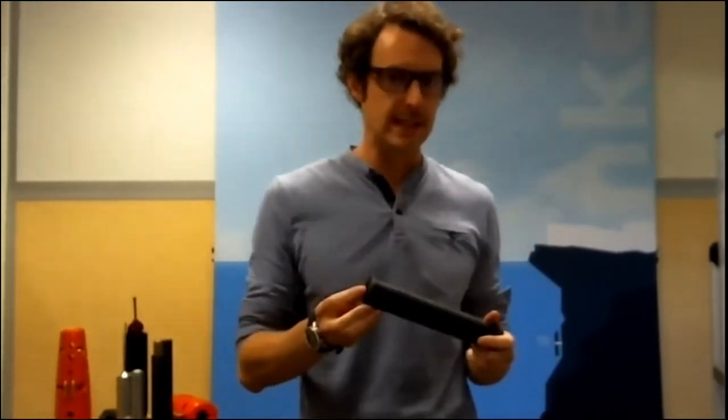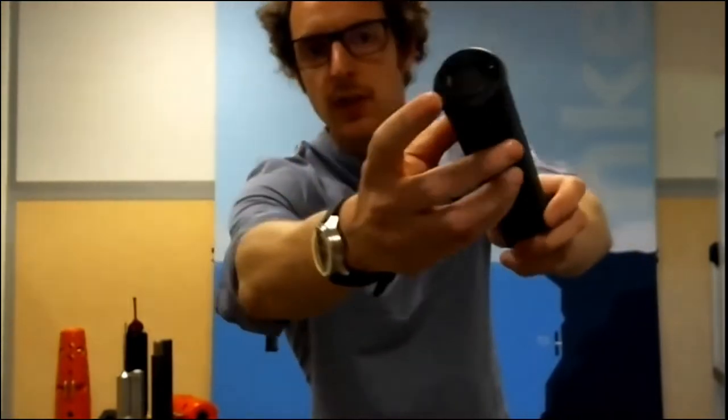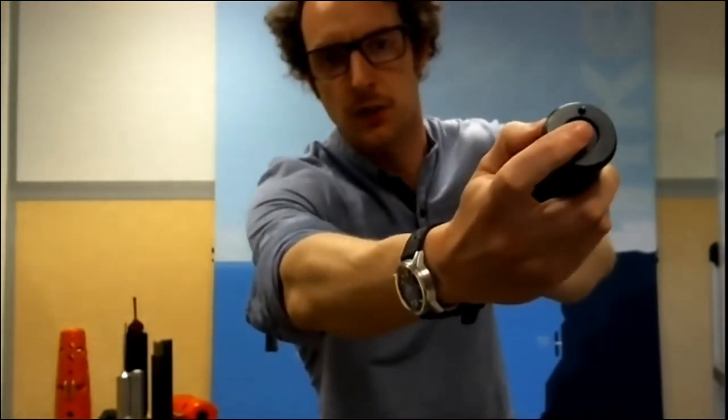So first, now what I'm holding is a Ysense TD, that could also be a Ysense wave. I will talk about this a little bit later. So TD stands for temperature and depth. So all our Ysense have at least temperature and depth, and then more sensors. So this one is just temperature and depth sensor. So you can see pressure sensor here that is behind a protection and specific coating to avoid any fouling to come in, and temperature sensor that is slightly extracted from the housing in order to optimize its response.